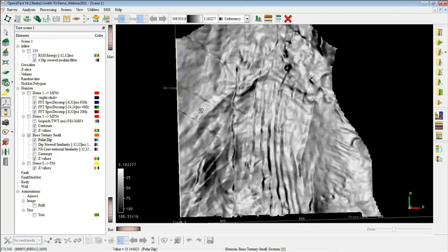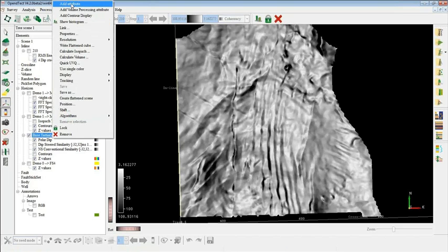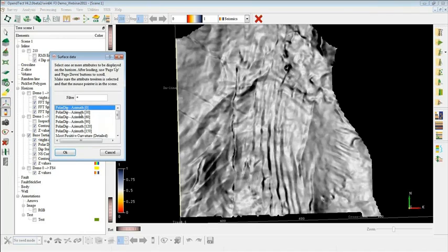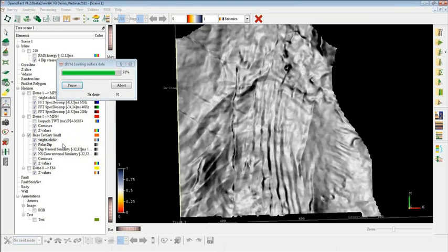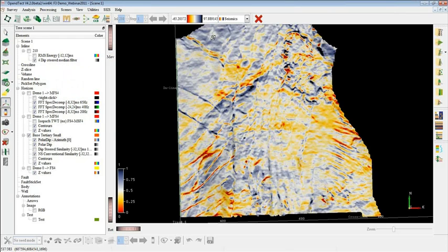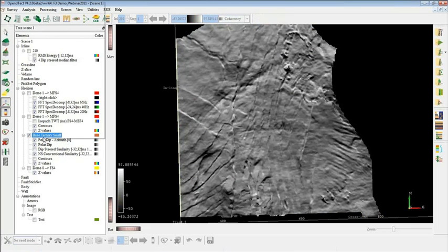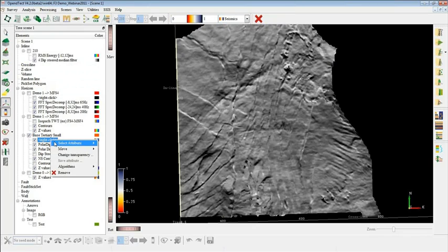However, you can rotate this way. I will create the attribute by creating apparent dips. The dips are measured at a certain azimuth, like looking from north, which is 0 degree from north, and you press OK, and you give it the same color. Here you go. And if you compare this thing with this one, you see a lot of difference in there. And I can look for another apparent dip, which is east-west surface data, 90 degree.